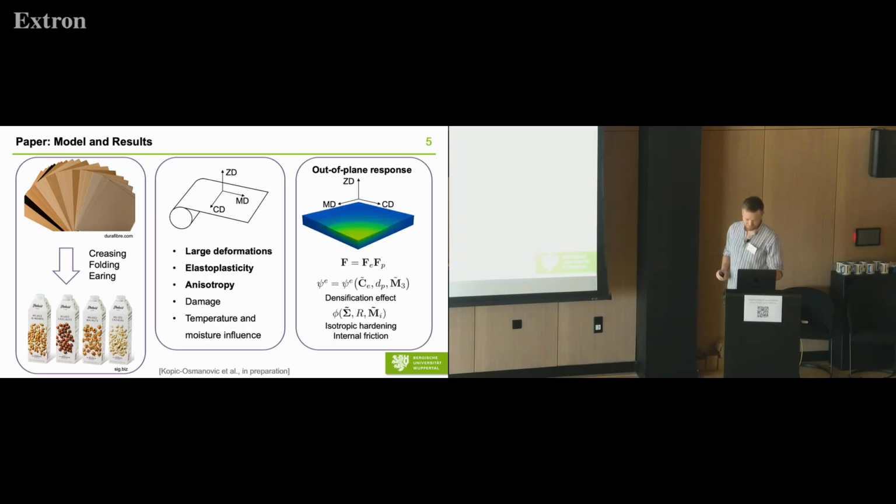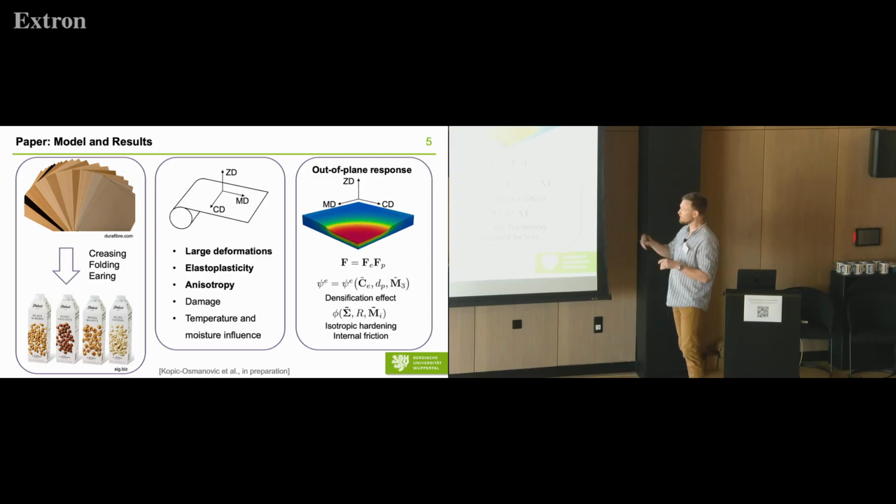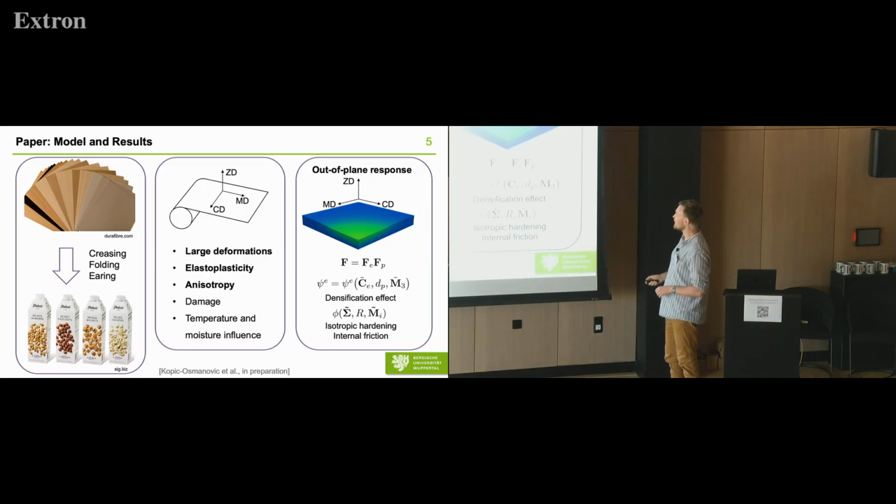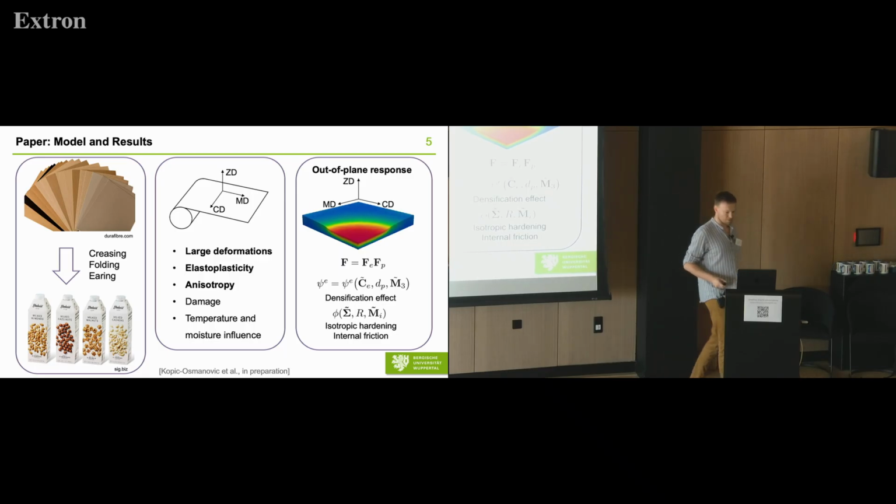Now we treat the in-plane and the out-of-plane behavior differently here. For the out-of-plane behavior, we need this multiplicative split. We formulate our Helmholtz free energy, our yield surface, and so on. And this is just a qualitative example here of a compression in out-of-plane direction.